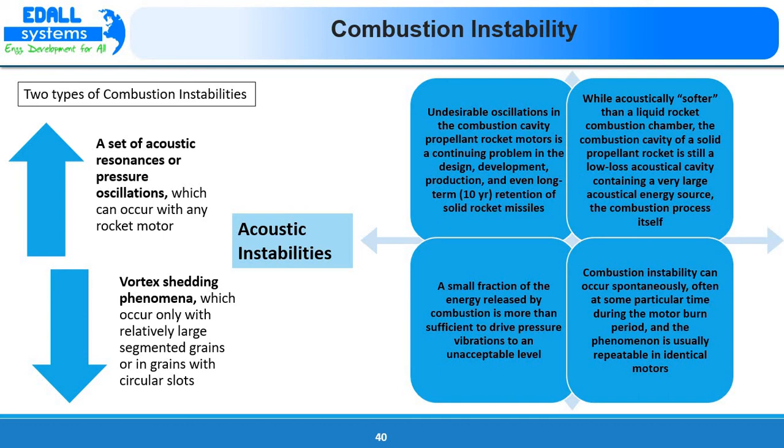While acoustically softer than a liquid rocket combustion chamber, the combustion cavity of a solid propellant rocket is still a low loss acoustical cavity containing a very large acoustical energy source, the combustion process itself. So a small fraction of the energy released by the combustion is more than sufficient to drive pressure vibrations to an unacceptable level. Combustion instability can occur spontaneously, often at some particular time during the motor burn period, and the phenomenon is usually repeatable